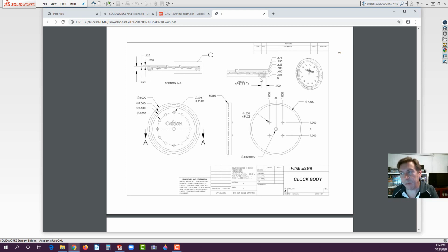And also this is just helpful in planning and or plotting out the depths of this clock. Okay, the overall diameter is 8 inches, and then there's a recess that's 7 inches in diameter, and it's cut 0.125 deep. Then there's another smaller 6.5 inch diameter, and then that's cut even deeper. The full amount is a 1/2 inch, but you have to subtract the 0.125 from that if you're going to build it on the floor of that first recess. So just be aware, it'll be 0.375.